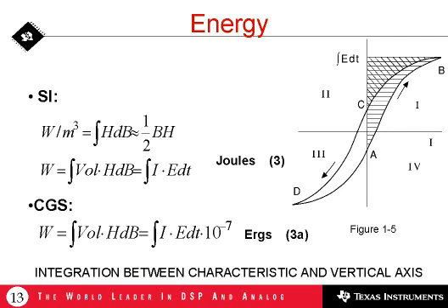As we're moving upward from A toward B, the voltage must be positive. Now, when we're down at A, we're below the horizontal axis. That means the volts-seconds at that point are negative, but the voltage is positive if we're moving upward. The fact that we're negative in volts-seconds at point A is simply as a result of history. We ended up at point A because of what happened before. But at the present moment, if we're moving upward, voltage must be positive. The volts-seconds, even though it's negative at A, is moving in a positive direction.